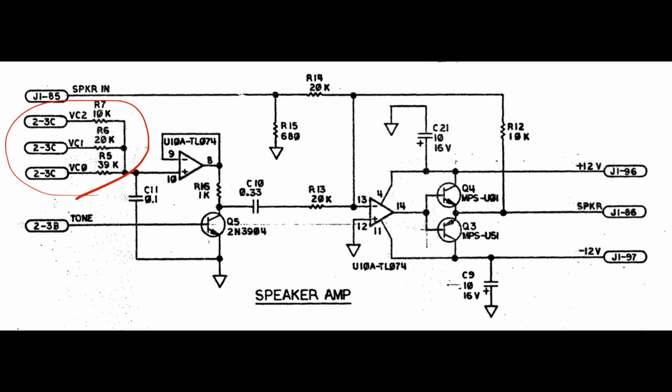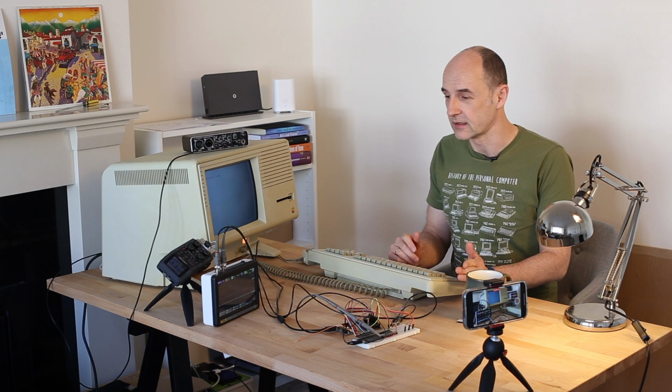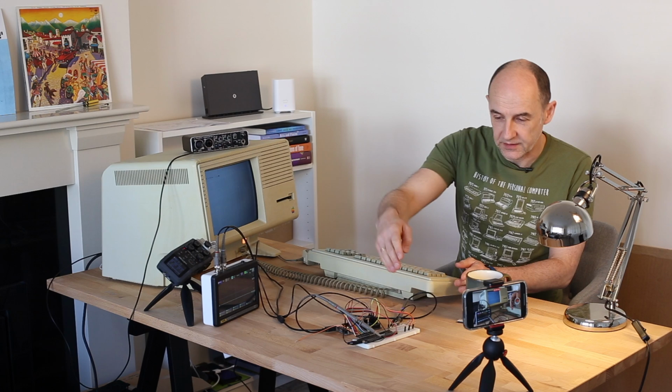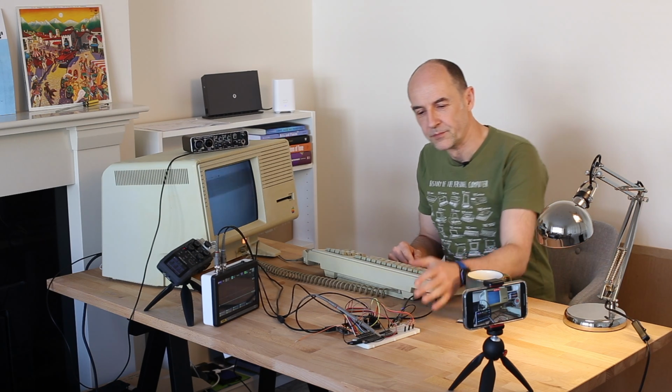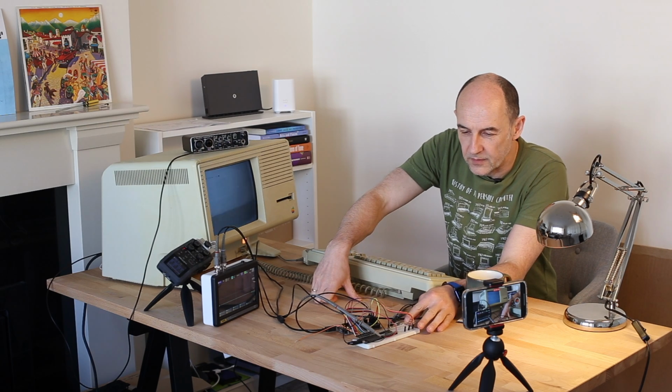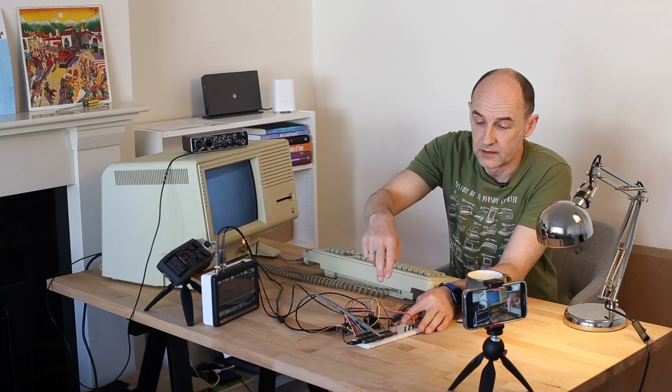The 3-bit resistor ladder used in the Lisa gives a programmer 8 different output voltages to select. That is 8 different volume levels. Similarly to the shift register, I wanted to experiment with a resistor ladder in practice, so I built a simple resistor ladder out of the resistors that I had at home and connected it to 3 digital lines.